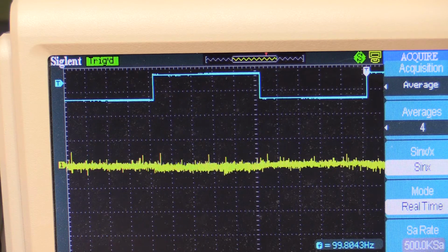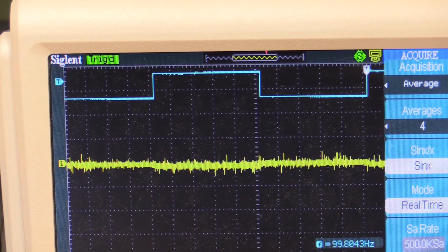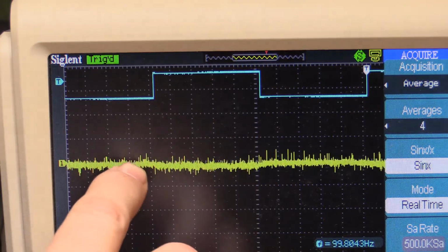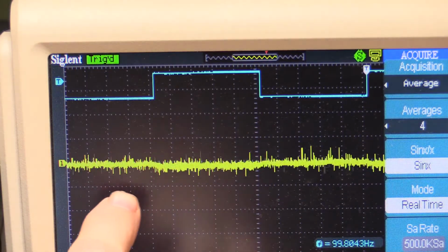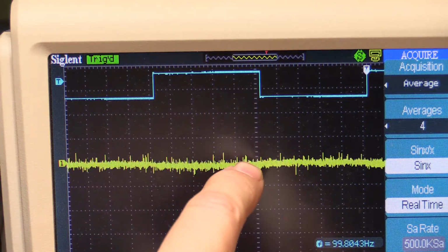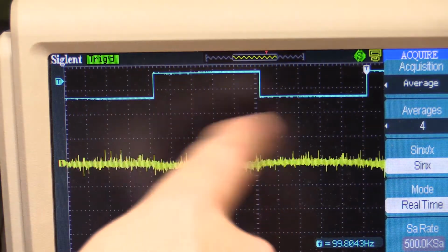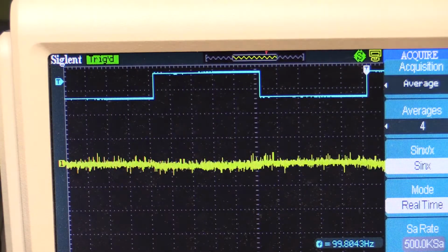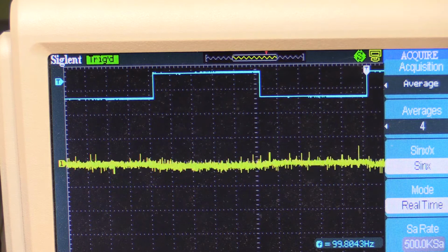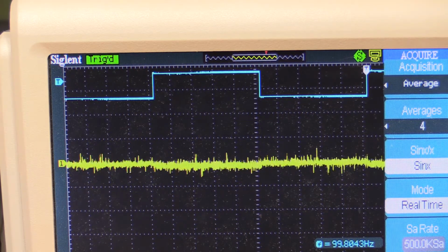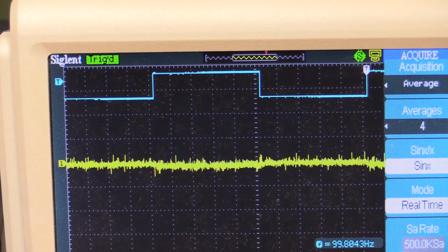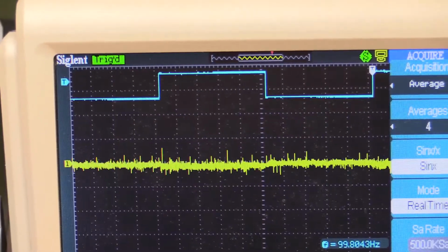What we're actually going to be looking for here is when this ramps up, because this is the 12 volt output, I would expect to see a pulse coming down here and then a pulse coming up here when the transients of this output switch on and off. But right now it's not, which is actually good because that means that it is really responding very nicely to the change in output load.